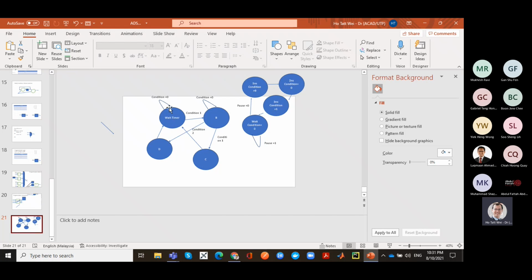So without this idea of nested states, your state transition machine could grow very big with so many states, and it becomes very difficult for you to track and to ensure correctness, right? Whereas if you break it up into subparts like that, you know that there are separate state transition machines. You can test these state transitions separately. Because this is a separate flip-flop and circuit, you can test this separately from this state transition, and then you can test the interaction.